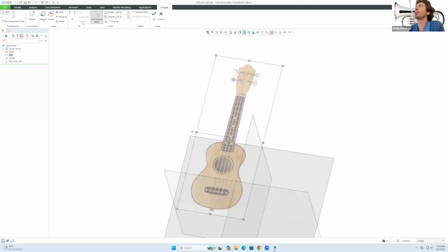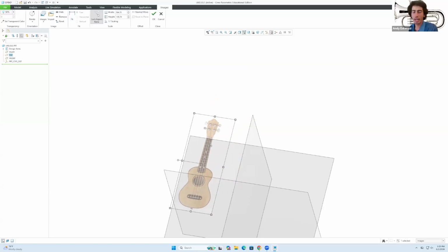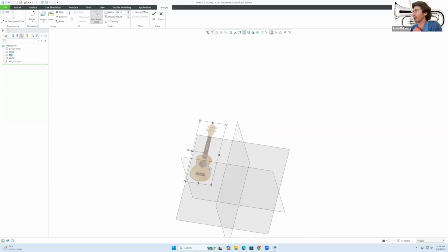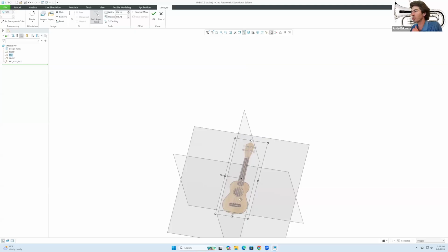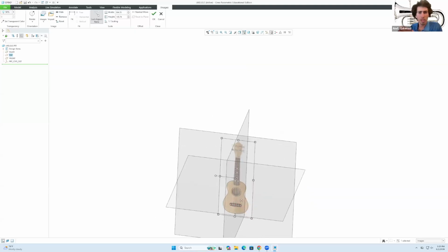You could do this thing over here that's called fit, where if I orient a point there and I orient a point there, and you told me that distance, because you happen to know it is 200, you can specify that, and it's gonna scale accordingly. Now that you actually fit it to your specified dimensions, you can move this. Super easy, nothing too fancy. In fact, today I will probably leave it like this.